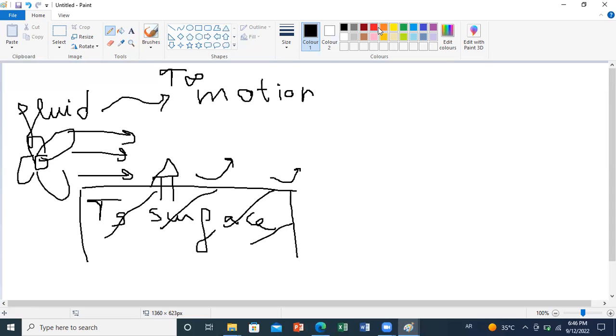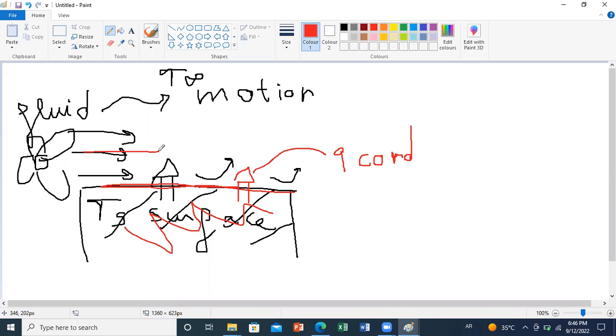Why do we say this? Because within the solid, heat is transferred by conduction. So at the surface level, when you consider the surface as a part of a solid, you have the flux getting out of the solid as a conductive flux. And this conductive flux will be transported by the fluid in the form of a convected flux.